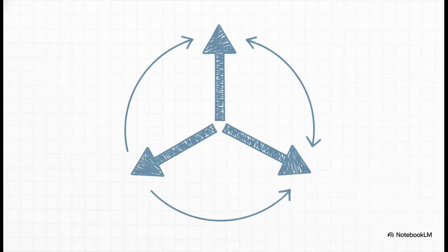Okay, so the absolutely crucial starting point here is the positive sequence. This represents the impedance offered by the network to the flow of positive sequence current. Picture a perfect, healthy system. In that ideal world, all the electrical quantities are numerically equal, they're perfectly balanced, and they are displaced from each other by exactly 120 degrees. This is the normal, forward-moving energy of the grid. Honestly, you can just think of it as the power grid's ultimate Zen state. It's that harmonious baseline where everything is behaving exactly as it should be.